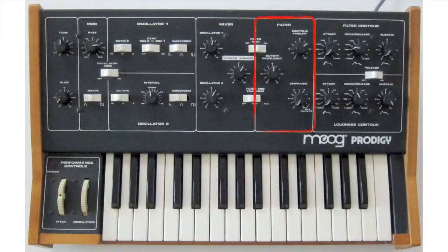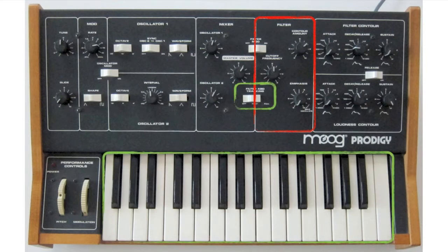For the second demonstration, I'll be showing you different configurations that can be used to modulate the VCF. In all these examples, it's the filter's cutoff frequency that's being modulated. We saw that the keyboard is a hardwired modulation source for the VCOs. The keyboard is also available as a configurable modulation source to the voltage-controlled filter.